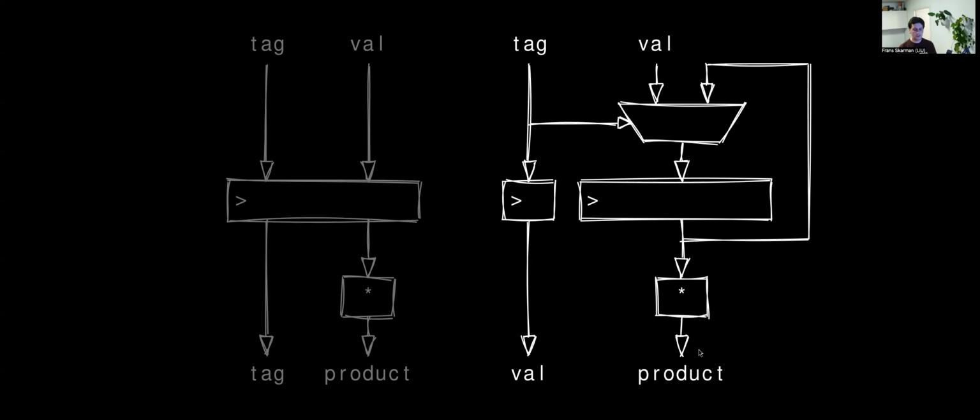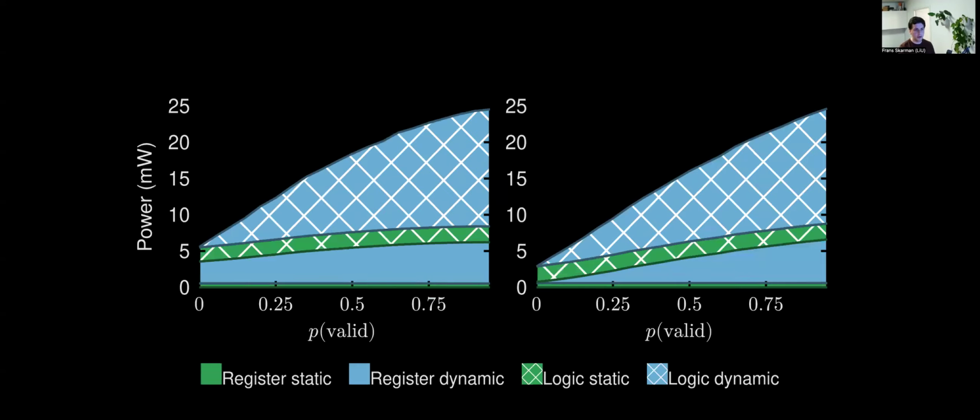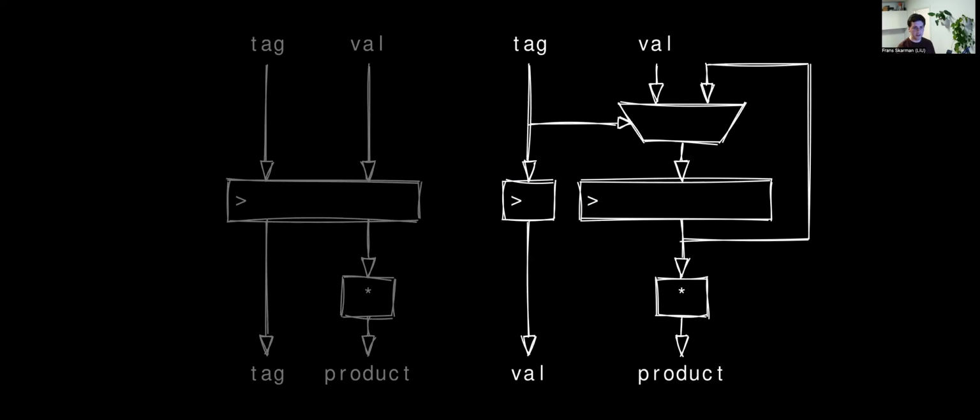And the synthesis is able to do some clock gating. You can see the switching power goes down a little bit here. So you can get some results from clock gating with Verilog, but the results get better when the compiler is more aware and can generate this hardware explicitly, instead of having the synthesis tool infer design intent and then do the optimization.